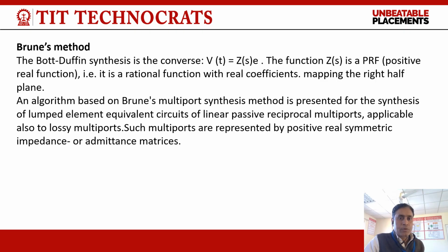An algorithm based on Brune multiport synthesis method is presented for the synthesis of lumped element equivalent circuit of linear passive reciprocal multiport, applicable also to noisy multiports. Such multiports are represented by positive real symmetric impedance or admittance matrices.